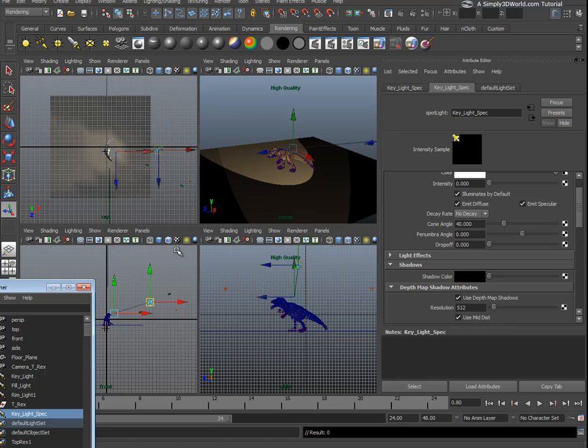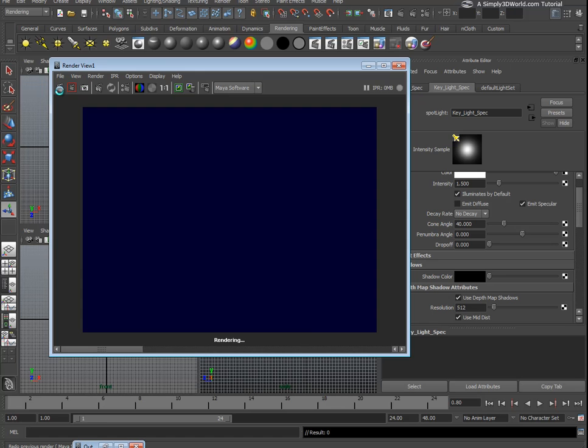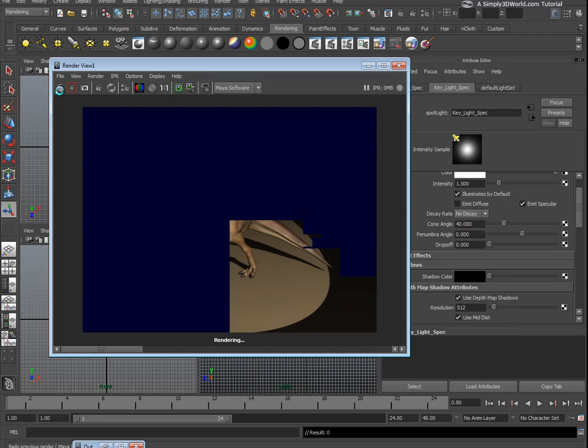So here you can see this is my spec light. So you can use these lights. I've got it exactly in the same position as my key light. And if you look now, I'm going to use this one only to boost specular highlights in my object. So I'll set it to emit specular only. And therefore you can do this because you couldn't turn the intensities for your key lights up a lot higher, but if you wanted to get a glistering sense, you could use separate spec lights in the same position as your key lights as well.